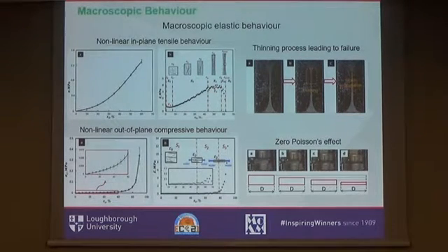Another interesting point to understand here is that, in contrast to the continuum, as in typical microstructures, we have a zero Poisson's effect. You can see at the same scale the specimen in compression, and practically here it shows schematically that its diameter doesn't change. It's clearly because when you're compressing there is no lateral extension, because the water is flowing out, and then it is being compacted on itself.